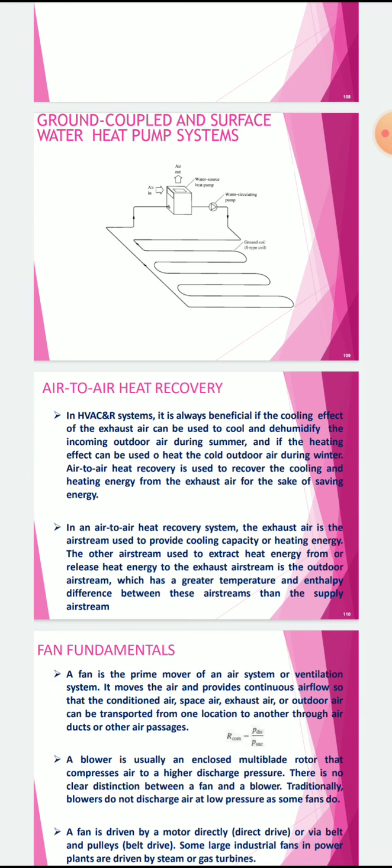The air to air heat recovery. In HVAC and refrigeration, that is heating, ventilation, and air conditioning and refrigeration systems, it is always beneficial if the cooling effect of the exhaust air can be used to cool and dehumidify the incoming outdoor air during summer, and if the heating effect can be used to heat the cool outdoor air during winter.